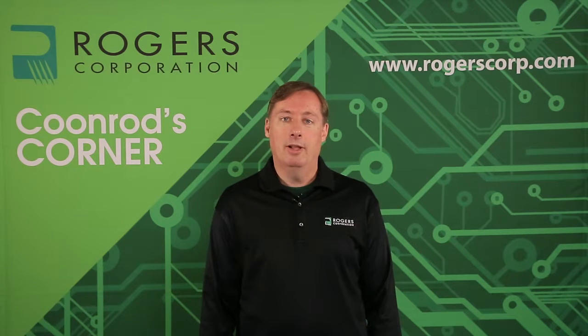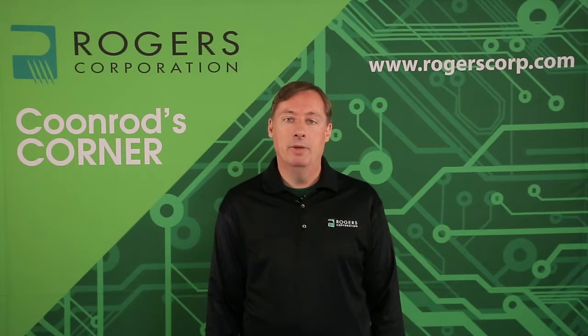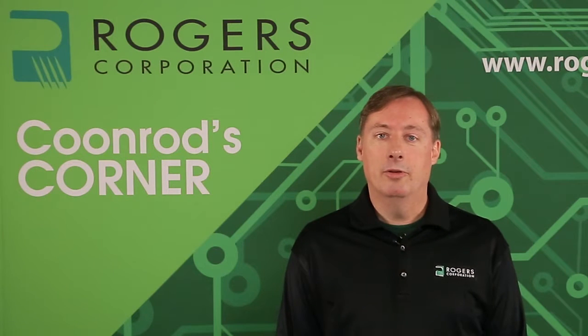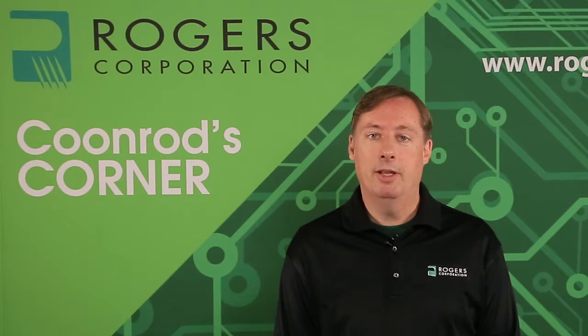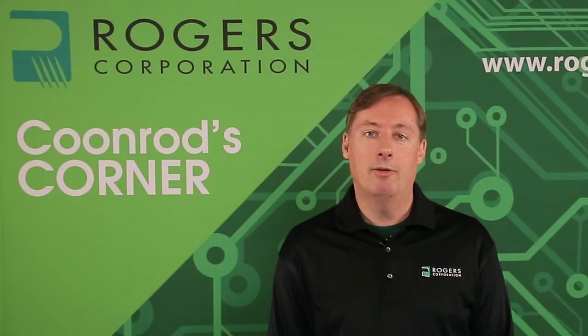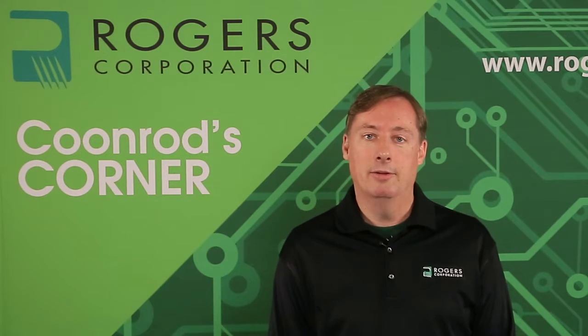Now, the LoPro technology is basically a low-profile copper, which means it's really a reverse treat copper. It's very smooth, and having smoother copper gives some benefits to the materials. The RO4000 materials are very well known to be used in high multi-layer applications, also has very good thermal conductivity and very low loss, and all that remains the same even with the LoPro technology involved with the product.